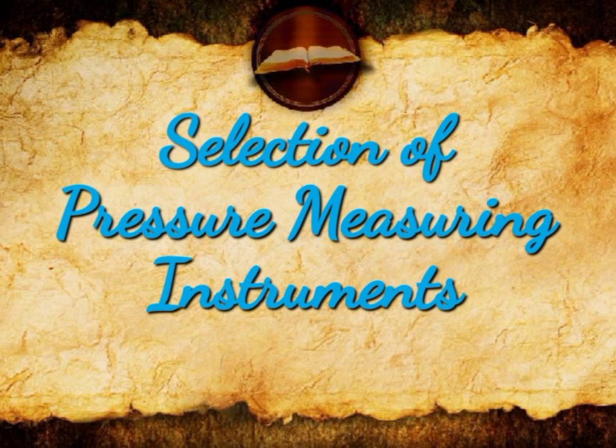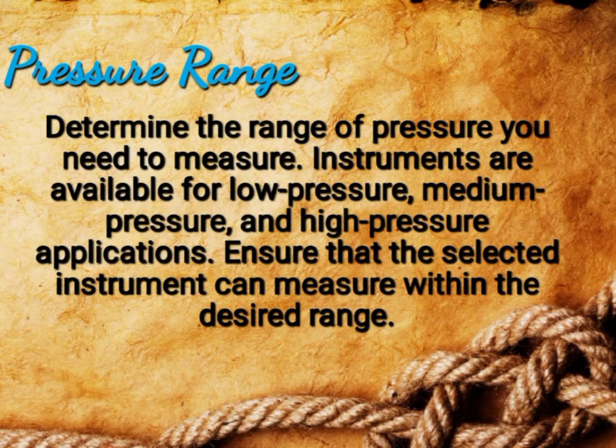So now let's move on to selection of pressure measuring instruments. So first is pressure range. Determine the range of pressure you need to measure. Instruments are available for low pressure, medium pressure, and high pressure applications. Ensure that the selected instrument can measure within the desired range.